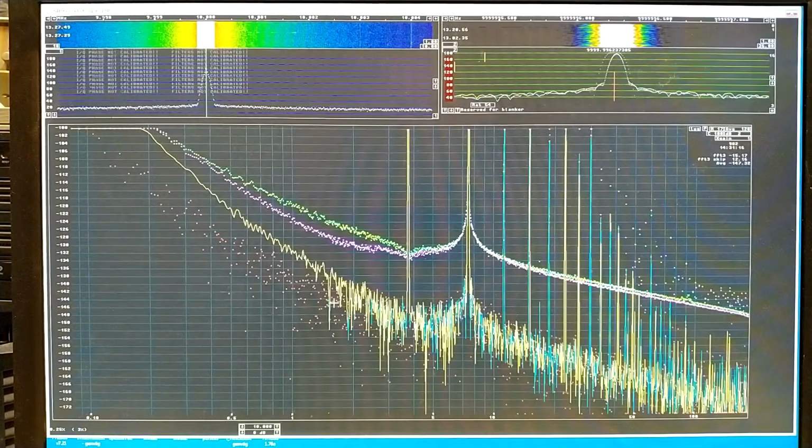And when I look further away, above 2 Hertz, the signal to noise ratio is far from good enough. You can see that the red dots, which is the imaginary part, have the same level as the yellow. And there are also blue dots down here in the noise occasionally, which means that the correlation is negative.